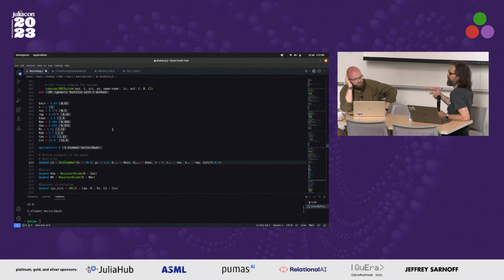But we have defined, for example, the whole four chambers. So we've got a heart element and things like that. If you want to follow the published heart and want to use that and don't want to mess with the valve functions, you can just use that and define that once, and then play with different circuits and different combinations, different branchings, etc., without messing with this one element. If your systemic circuit is always the same, define a systemic circuit, leave it, and just use that as one element with two connections, which makes your connect tree much more manageable.